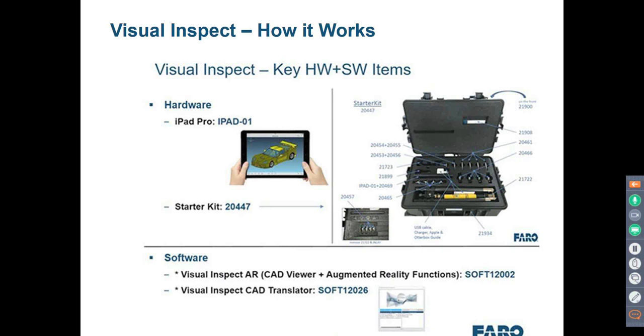And you have an editing system on the iPad where you can do the same in your virtual model. So you don't have to prepare any data for special augmented reality use. You can just use your normal CAD model and make virtual markers there on the same places. Then you point the camera at your object, and as soon as at least 4 markers appear in the view of the camera, we can overlay it.